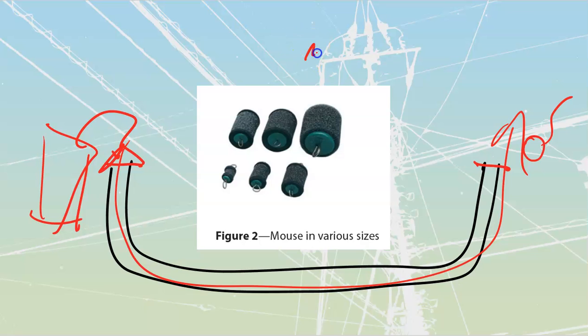Then we have another one called a mandrel, or sometimes spelled mandrel. What those are designed to be is they're rigid ones that look like this. They make sure that the conduit is sized, that it's not collapsed. If you've got a mandrel, you're going to pull that thing in and you're going to make sure the conduit has not been collapsed.